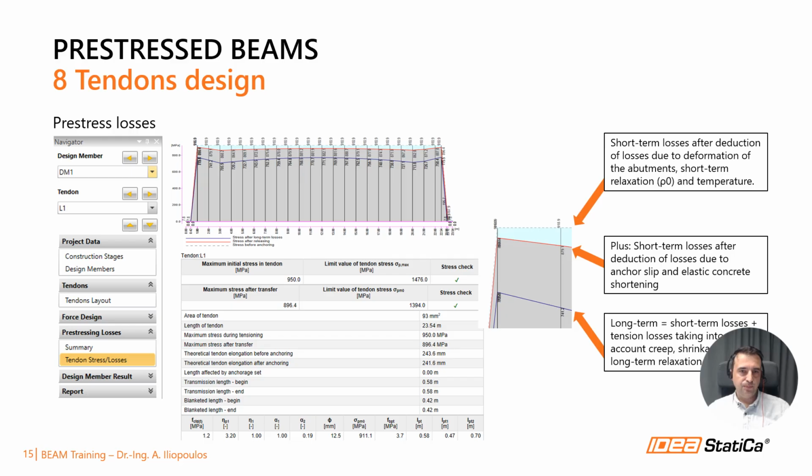It's advisable to always check these results, and if there are big differences between the stresses, there may be a mistake in the definition of prestressing.